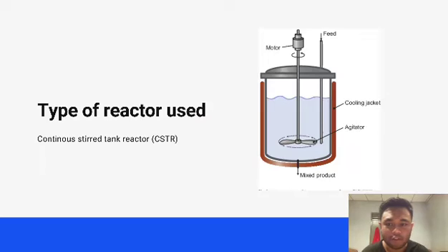So for the type of reactor, we have chosen the conversion reactor. The conversion reactor is a CSTR that specializes in conversion reactions. It can only work with reaction sets that include that reaction type. The reason we choose this reactor is to control the conversion rate.